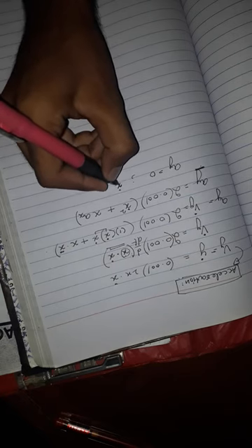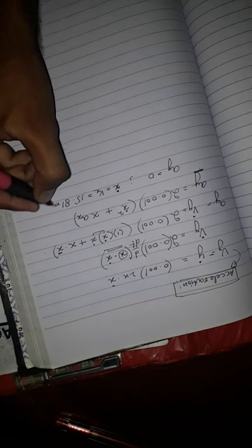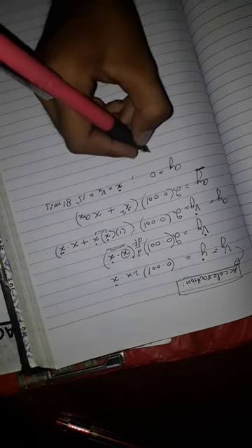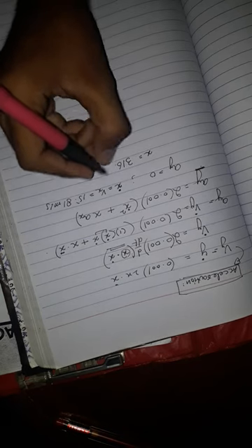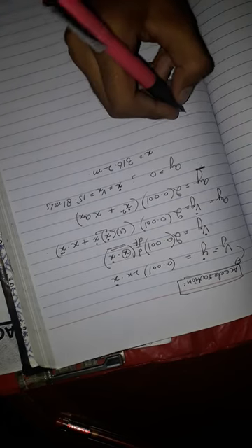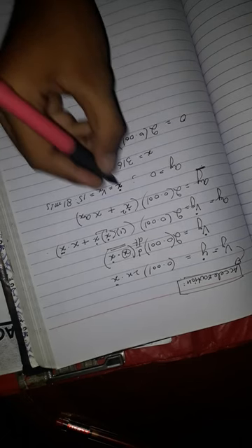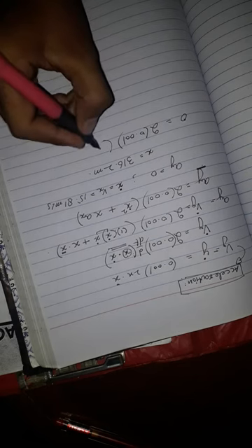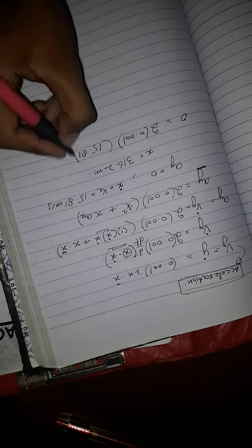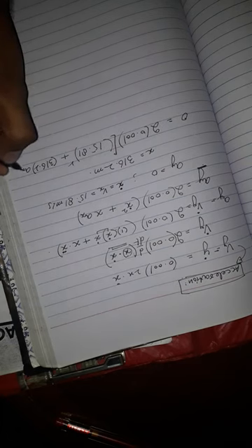The velocity in the x direction that we have just calculated, that is what, 15.81 meters per second. And the x is what, the horizontal distance we calculated at the start of the problem. But now we are substituting these values. 2 into 0.001, this is ẋ, here is its value 15.81 and its square, plus x, this is 316.2 into ax.